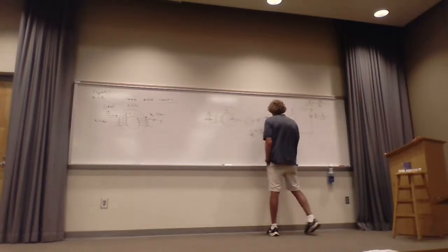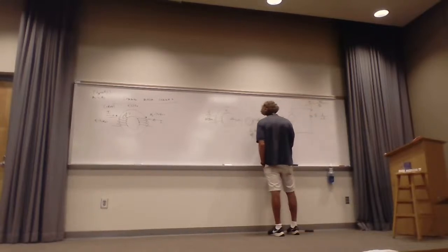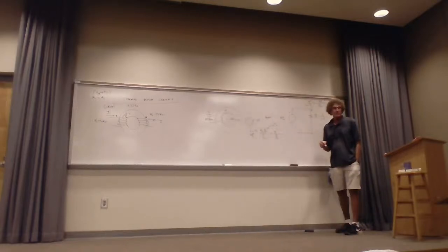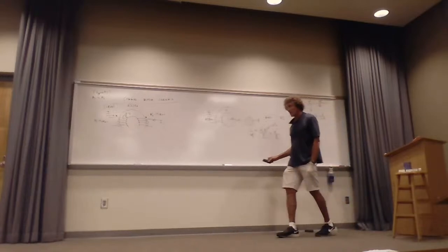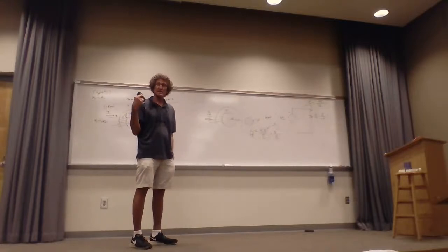It would be what? Just N I over the reluctance times N, or N squared, right? And inductance is always proportional to the square of the number of turns. N squared divided by the reluctance. And that's the way it always is. Now you see, that's the self-inductance, right? To get the mutual, the only difference would be what? Are y'all with me on this? I don't hold you responsible for calculating this, but it helps to appreciate this for where we're going.